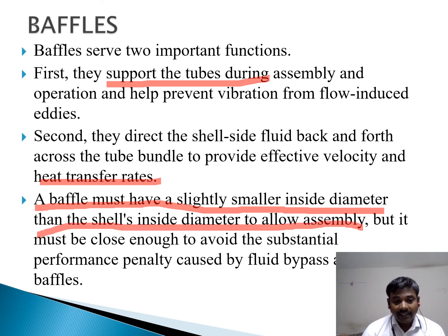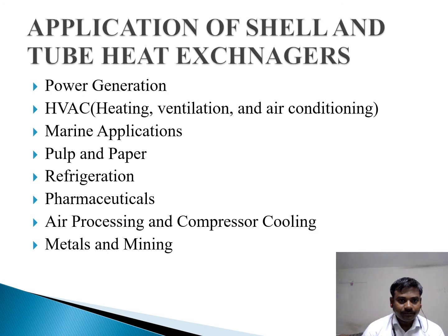If you have a large baffle compared with your shell, what will happen? You cannot fit your baffle inside your shell and tube, or you cannot place your baffle inside your heat exchanger. So the condition for fitting your baffle is that it should have a slightly smaller inside diameter than the shell inside diameter. Then only you can fit the baffle inside your shell and tube.